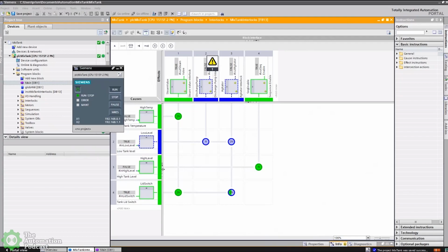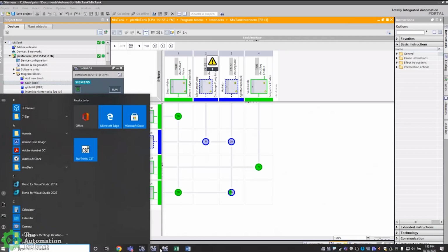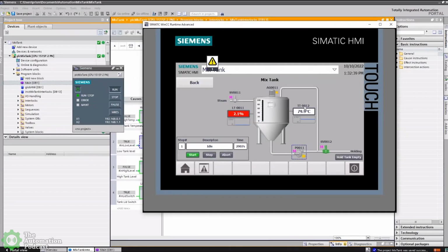That's awesome. So for the audience members who aren't familiar, this is a free PLC simulator that comes with TIA Portal. It's not extra. It just comes with it. We covered this in my course. It's actually really easy to use. It's such a nice add-on. And John, I think it also simulates HMI too. I mean, that's what we're looking at here, right? Yeah, absolutely. Like Ron mentioned, that's what I was using on my demo when I started. I always use PLC Sim because it supports all the controllers. It has some PLC simulator tags that I can use. And when I simulate the HMI, what's great about TIA Portal is if the HMI starts up and launches and looks for the PLC on the LAN network, but finds PLC Sim is launched, it'll connect automatically to PLC Sim.